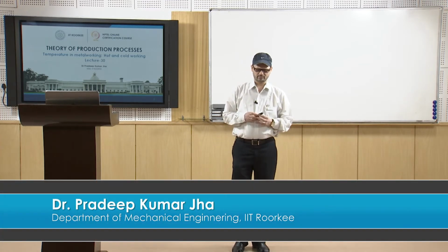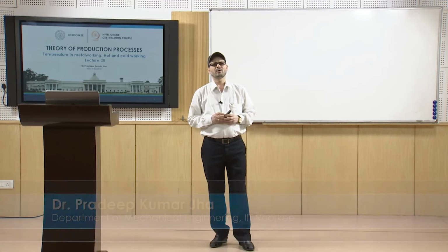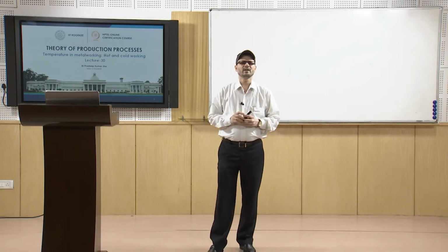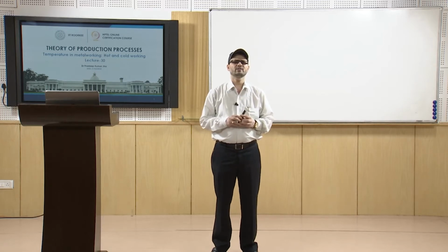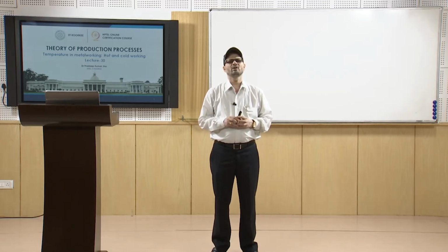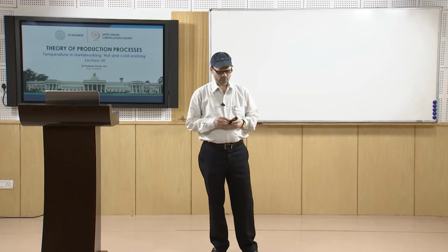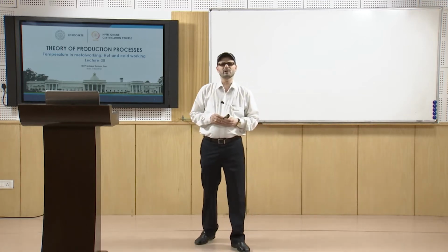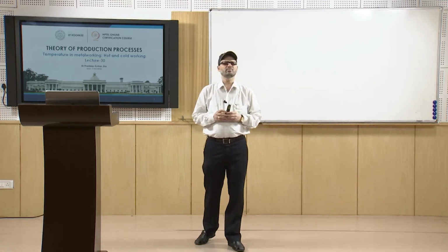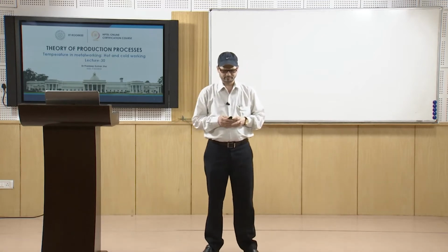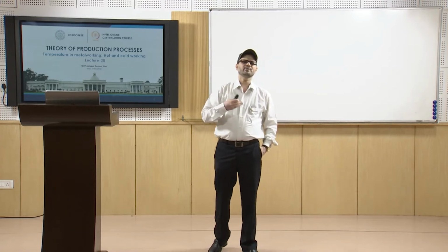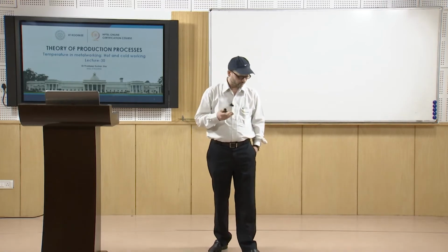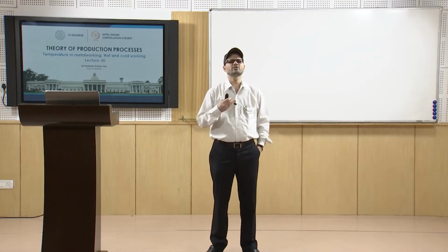In this lecture we are going to discuss the effect of temperature in metalworking, and typically we will be talking about hot and cold working, or hot and cold forming. We discussed the metalworking processes, and as we discussed, temperature has a role, because once you increase the temperature, the flow stress required is decreased.